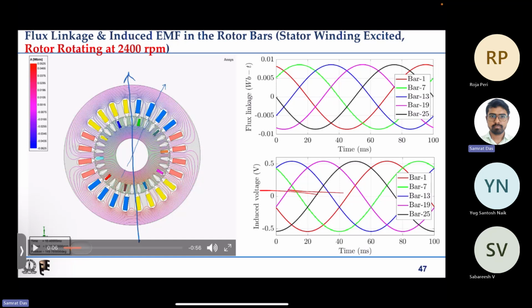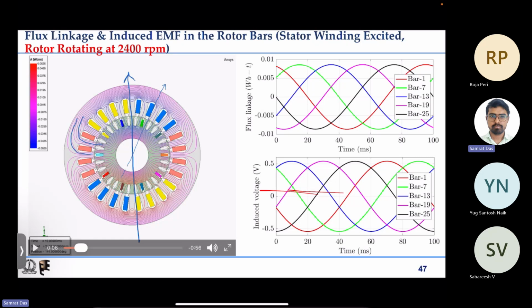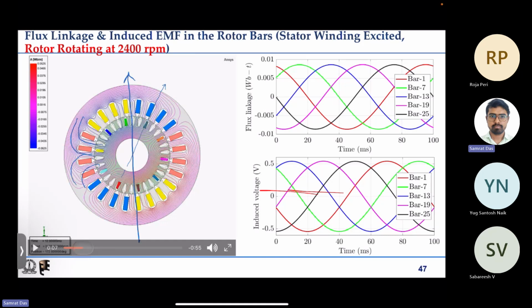Now if I go ahead and probably go here, you'll be able to see that actually there is no net flux linking the R phase conductors, because whatever flux these two conductors are enclosing, they are also enclosing in the reverse direction for these two cases. So here if it is clockwise, here it has to be anti-clockwise, so net there is flux linkage equal to 0, right?